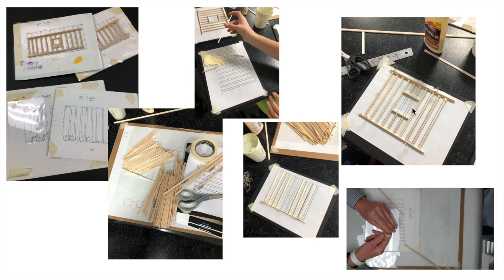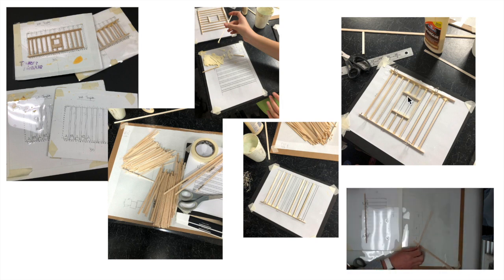Include windows. I would sketch those beforehand on a couple of templates. They should be all the same height. If you want them the same height, think about the size of the window, obviously, that you want to create. Make sure you have a sill plate and a header for those as well. And you'll do the exact same thing for your doorways. Make sure you have a piece of balsa that is identified as a header in there, and make it at least 3 studs wide so it looks somewhat realistic.